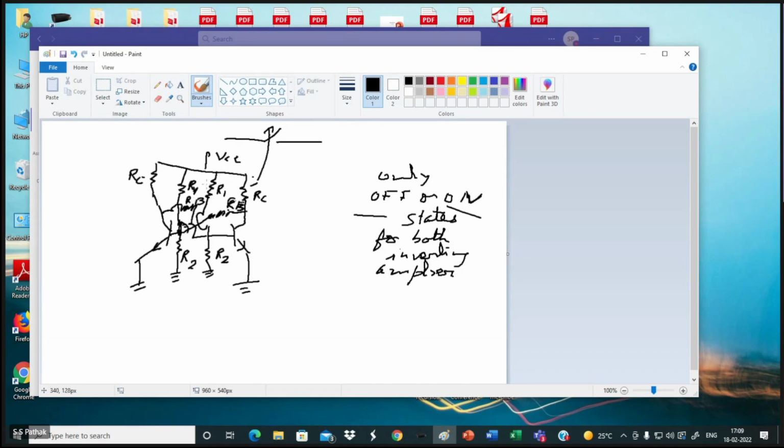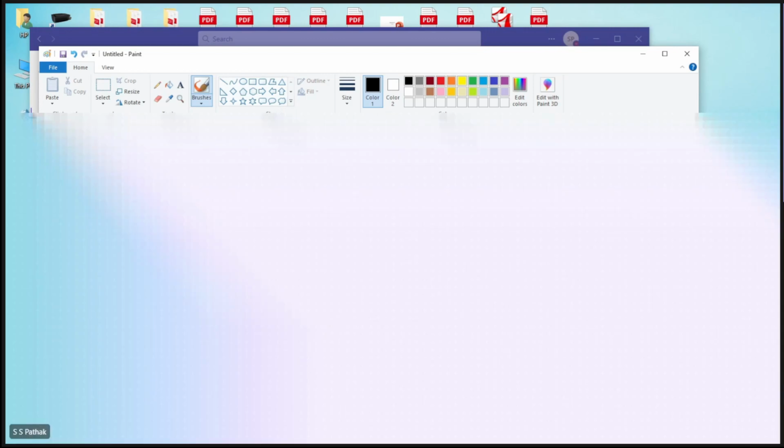So I have switched on the circuit. After that, some noise has come, some sparking has come, maybe some thermal noise, maybe something that is converted to electrical form, and it has changed this current, let us say. This is changed by delta IC. Let us say delta IC increases. Noise has disturbed the design current that I have set for both of them. I don't know which one is going in which direction. Until noise comes, they remain stable because both are identical, so nothing is acting on that. So this has increased by delta IC.